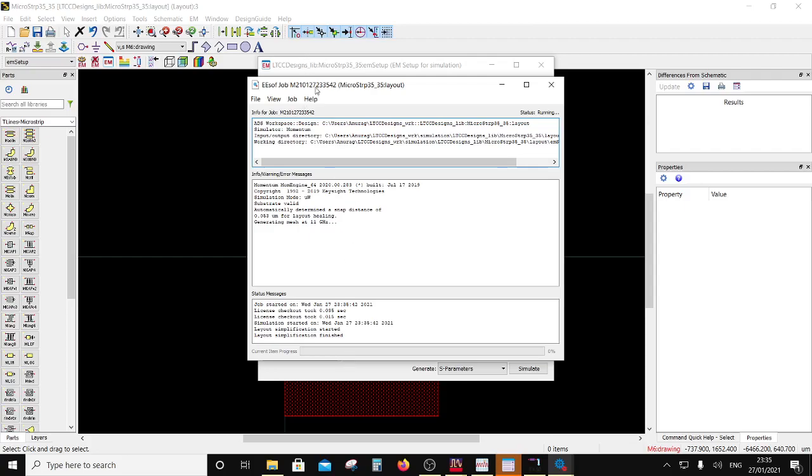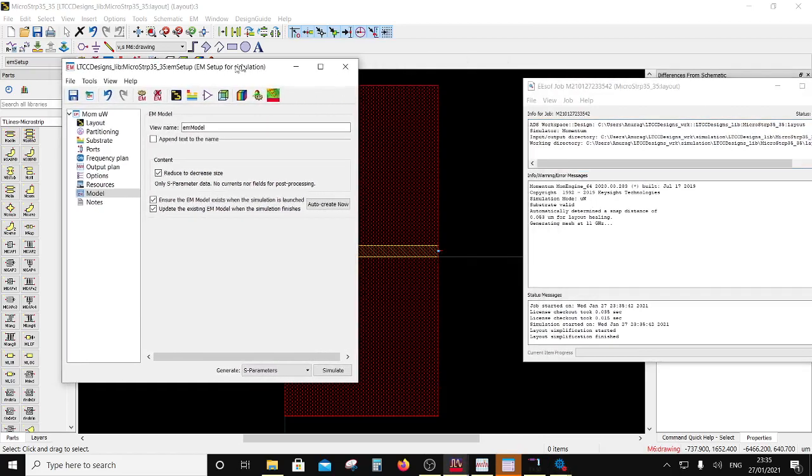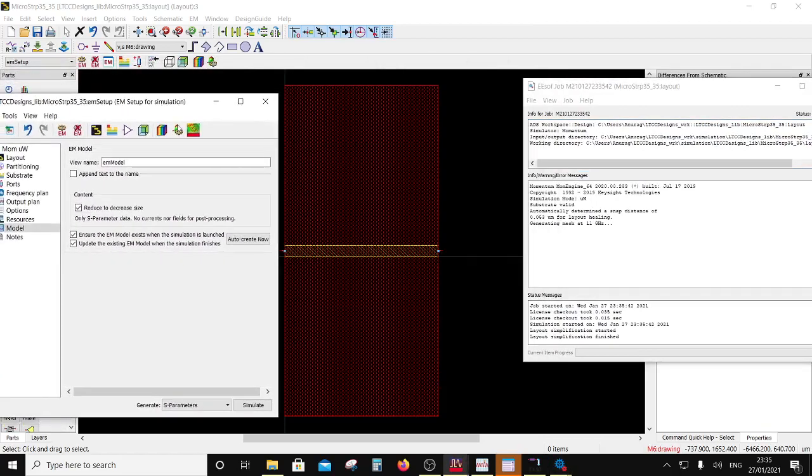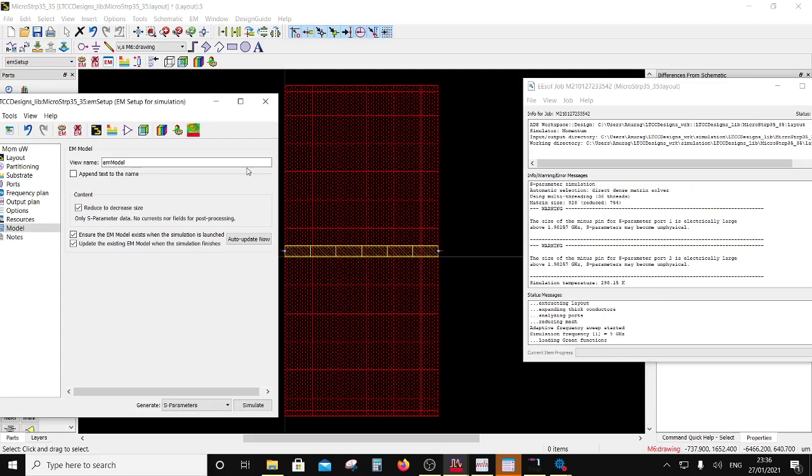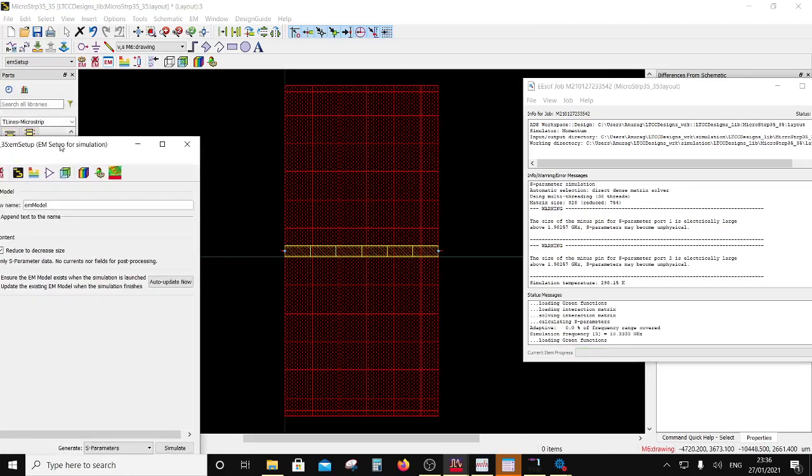So it's going to mesh this, and I'm going to make sure that this is 35 ohm. Even if it is not, what I have verified in the previous session is that EM Pro FEM is validating that the line cal is very accurate. So I'm not going to change it even if it is not 35.35. It has to be in the same ballpark. That's the whole idea, right? So it has to be near the center of the Smith chart.